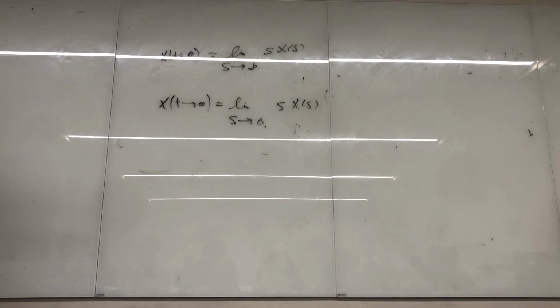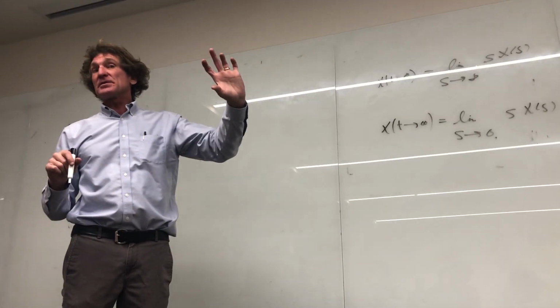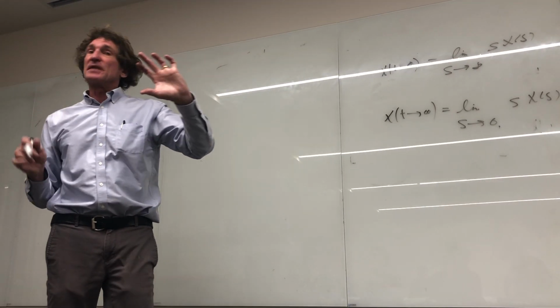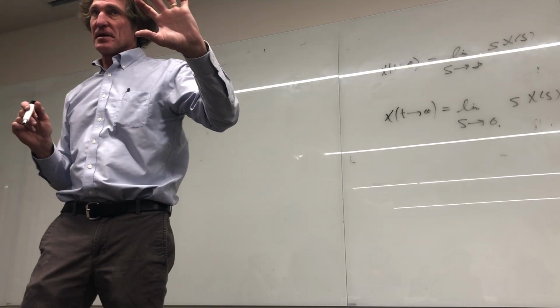A stable system would be something where you've got a battery and you flip a switch, and you have a capacitor and resistor, and you want the voltage across that capacitor, which was 0 initially. Well, the voltage at t equals 0 is 0, but it will gradually grow at the rate of a time constant, 1 over RC, until it's charged to the value of the battery. That's a marginally stable system, because the voltage doesn't go to 0, but it doesn't go to infinity either.